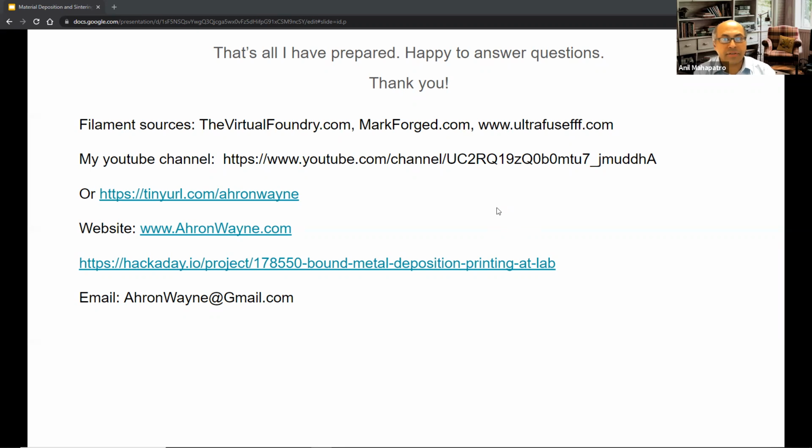So what are the differences? I know some of them you pointed out in the slides, but the ones you haven't, what would you say would be some of the key factors in getting a more densified product, looking into the variations in the materials? A densified product, for ceramics and glass, I think it's primarily temperature. I think you can probably just keep upping the temperature and you'll get a denser and denser part. For metal, the problem is if you increase the temperature too much, it'll melt. So in industry, they can get very, very close and very precisely right up to the melting temperature, but not quite. But with my setup, it's just a little bit more janky.